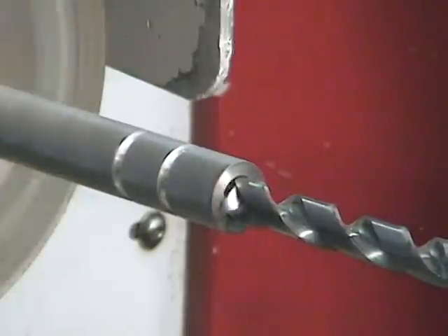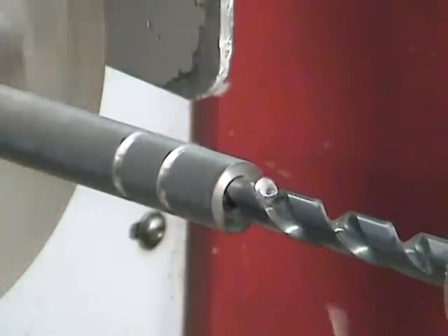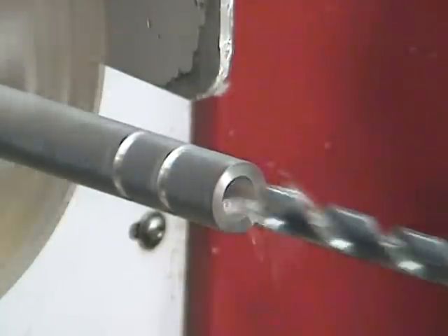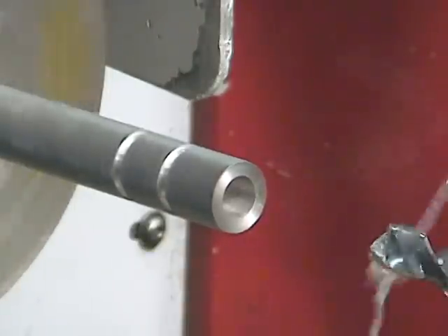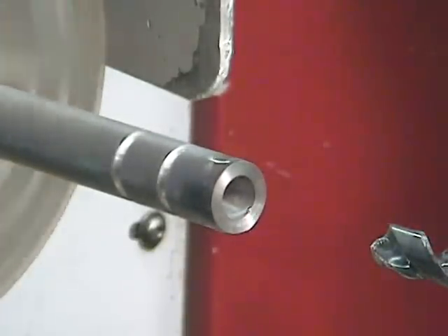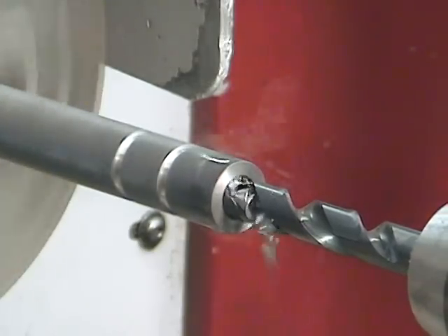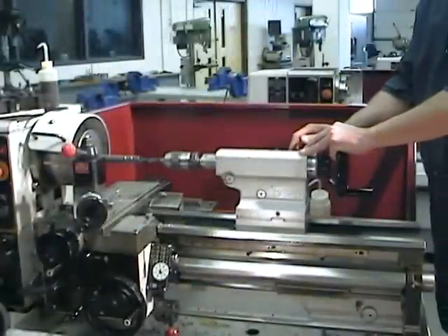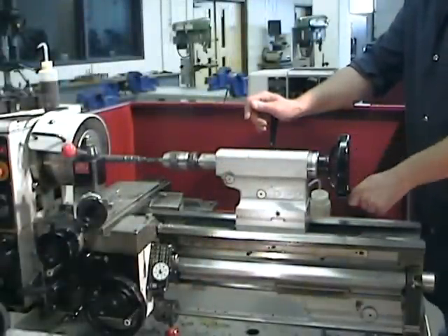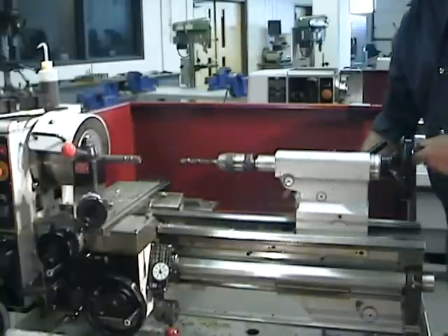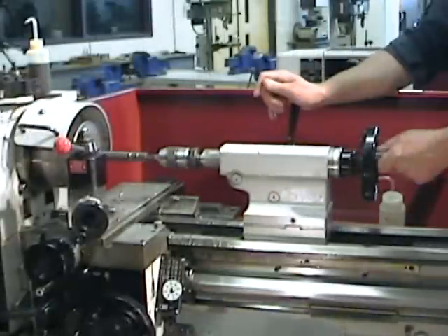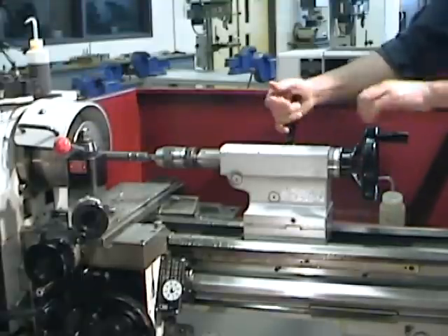So here's those clips. As I've mentioned several times before, when you start a drilling cycle, you can drill up to 3 times the diameter of the drill in depth without retracting. But if you go past that, you're going to want to start to perform a peck drilling cycle. So retract, cool, flush your chips, and drill again. Note that the deeper that you get into the part, the shorter that the cutting period becomes. In other words, when the drill is in the part quite deeply, you don't want to leave it there for a long time, because when it is in the hole, it is rubbing, and that creates a lot of heat. So the peck drilling cycle accelerates with depth.